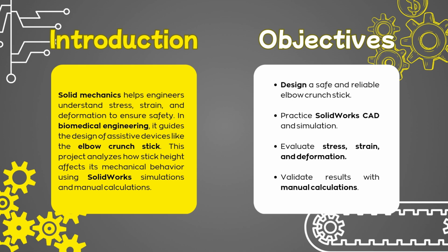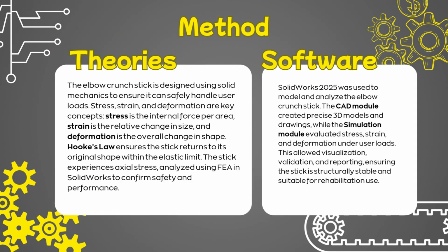We aim to propose a safe and reliable design, gain hands-on experience using SolidWorks for modeling and simulation, and evaluate stress, strain, and deformation. Manual calculations are also done to validate the simulation results. Our analysis is based on basic solid mechanics principles. Stress refers to the internal force within the stick. Strain describes how much the stick deforms, and deformation shows the overall change in shape or length.